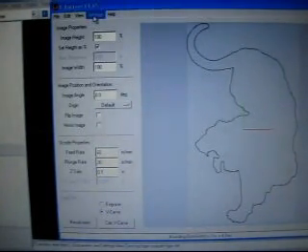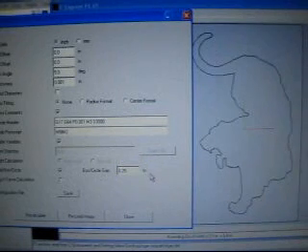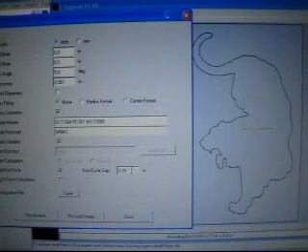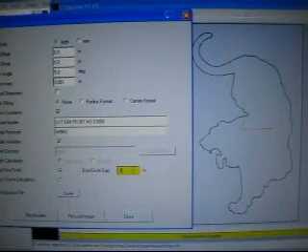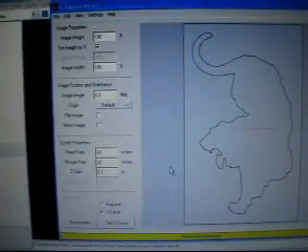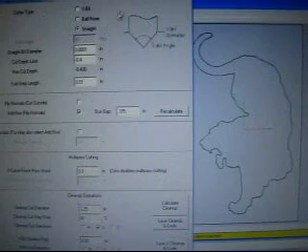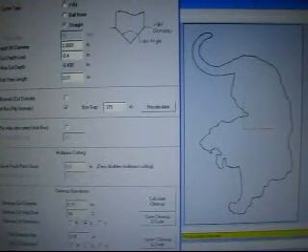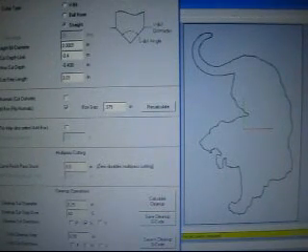So now what we want to do is go into our general settings and enable this bounding box, because we wanted to enlarge that box, the machining area, in order to get in there. Right now it's set to about a 1/4 inch box. I'm going to set that to 3.375, and just close it. I'm not going to save it, I'm just going to close it. So now when we go to our V Carve settings and do our calculation, we'll leave these settings all alone and calculate the V Carve.